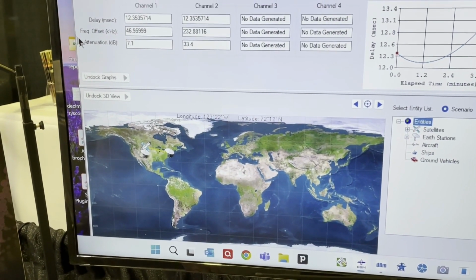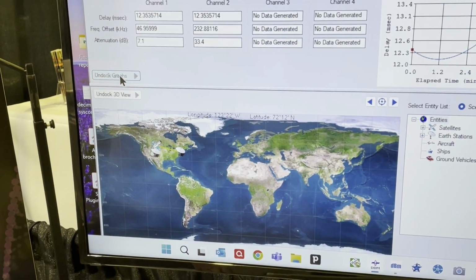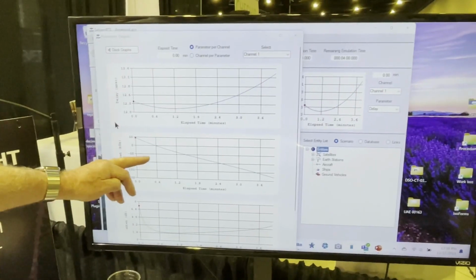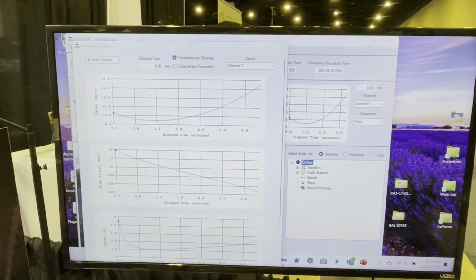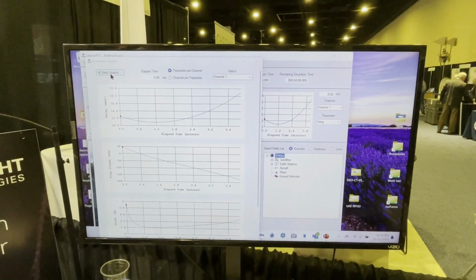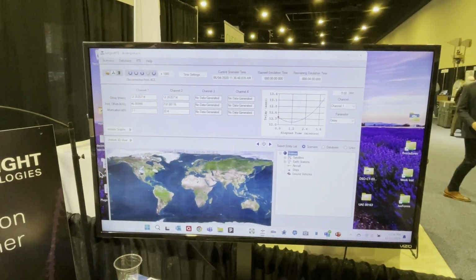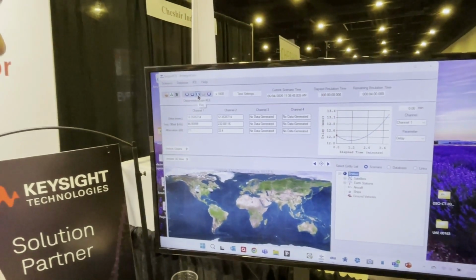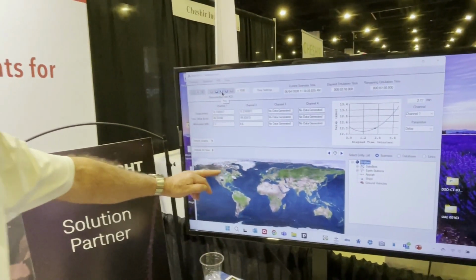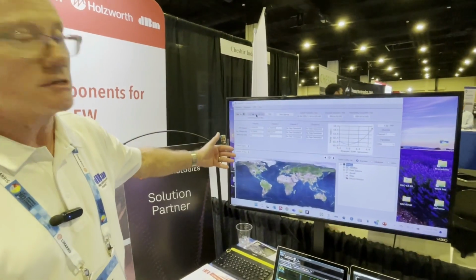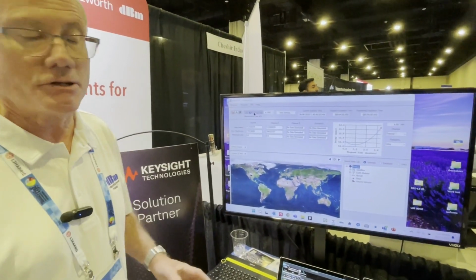We're using a Starlink satellite. And what will happen as that satellite moves across the horizon, we're going to get changing delays and Dopplers and signal attenuation. So if you were in a lab and you wanted to simulate this particular satellite, what will happen if I run this 1,000 times faster than normal, as the satellite moves across the US, we're going to get continuous change in delay, Doppler, and signal attenuation.